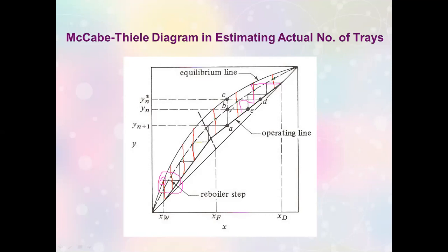Like AB to AC is your Murphree efficiency. So what you do, you measure all the lengths of this line and multiply it by the Murphree efficiency. Then measure from the right on your operating line up until that particular value that you took from the product of Murphree efficiency and the length of your line. Then you connect all those points. That would be your new equilibrium curve.